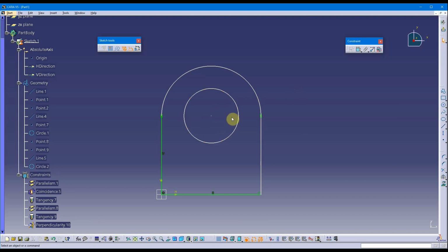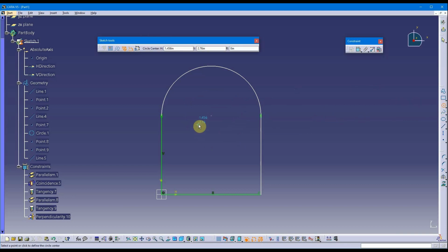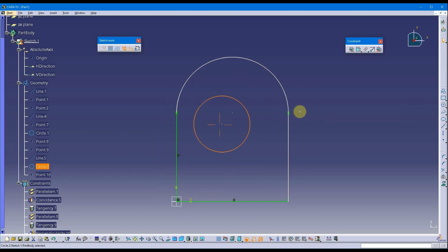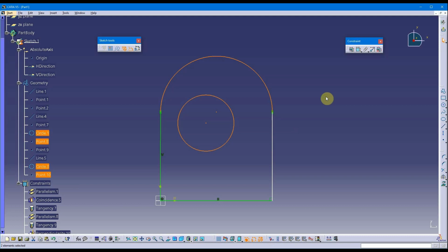Since I did a point-on-point snap, it doesn't show you a constraint, which is fine, but I want to do this instead just for demo purposes. I want to come in over here and just draw it off to the side. The concentric means essentially two parallel circles. So I can do a pre-select here and a pre-select here. Notice I'm going circle, arc. It doesn't matter whether they're arcs or circles, as long as they're circular in nature.